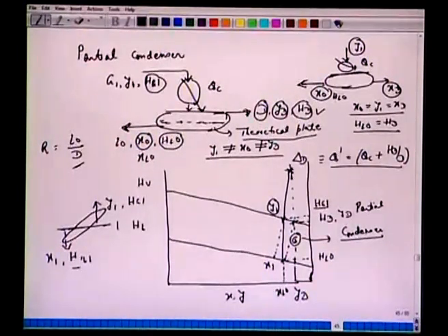The first tie line which we have drawn represents the partial condenser and the second tie line is stage 1. Again, we can connect with this differential line and continue with our construction. The more important point here is understanding the difference between the total condenser and the partial condenser.